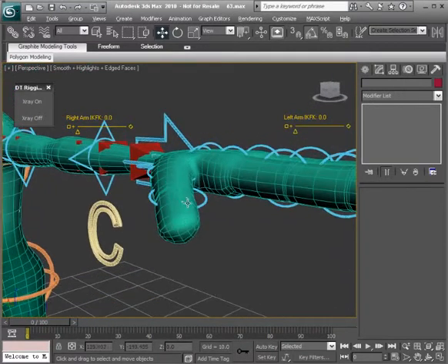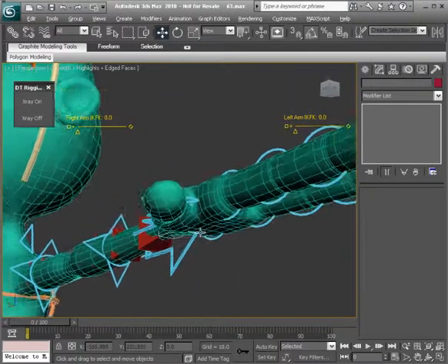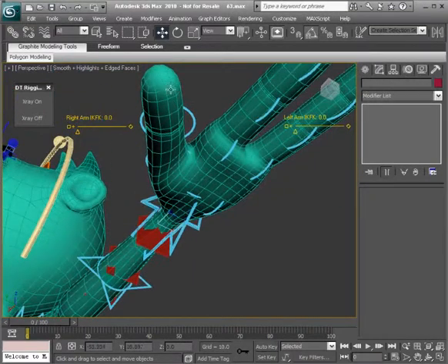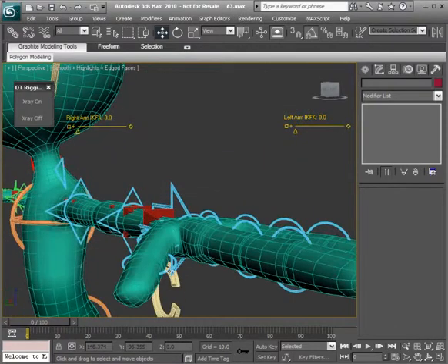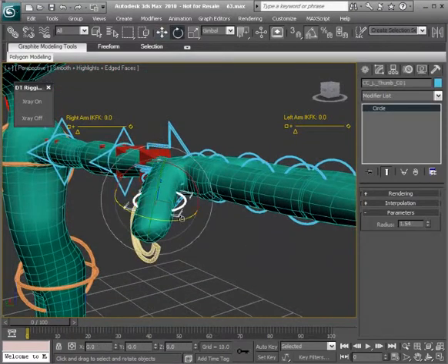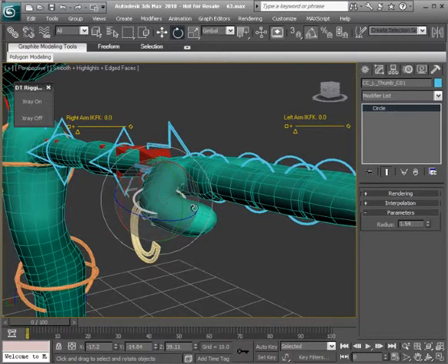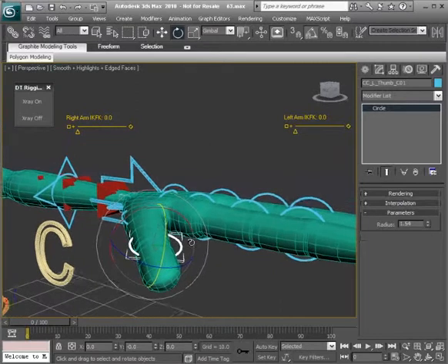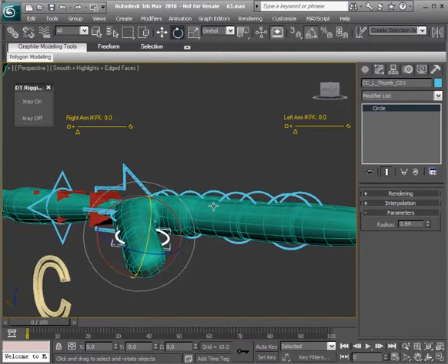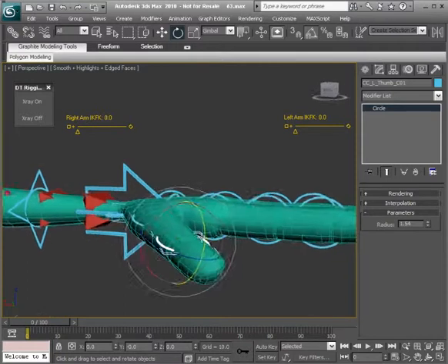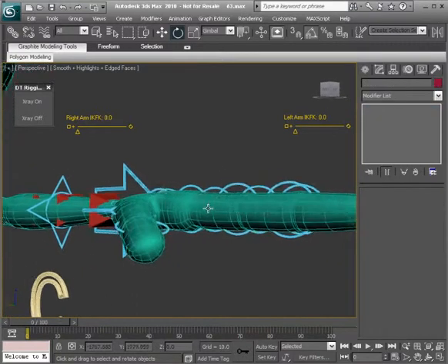You can see that our controls are not oriented to the character mesh. You can see that they're definitely at different angles. So when we bend this, it's not going to look right at all. I'll go ahead and show you that. Now, if it wasn't for the ability to save and load our envelope weights, this would be tedious to fix. We'd have to break the envelope, get rid of that skin modifier, go ahead and reapply it, fix our controls. It'd be a mess.